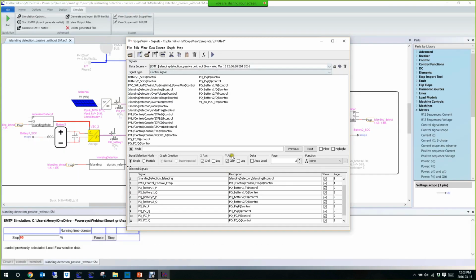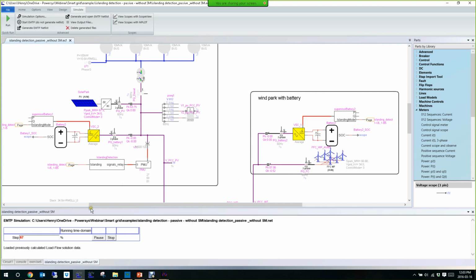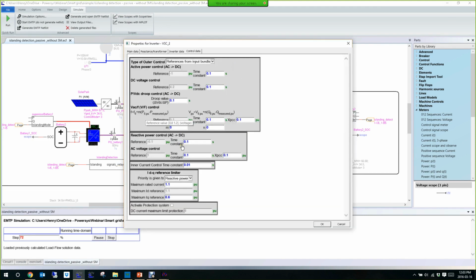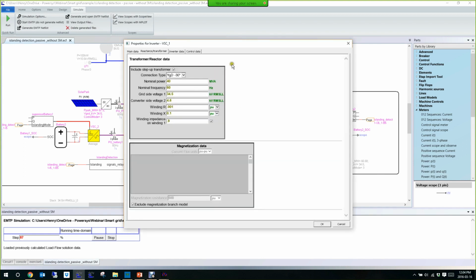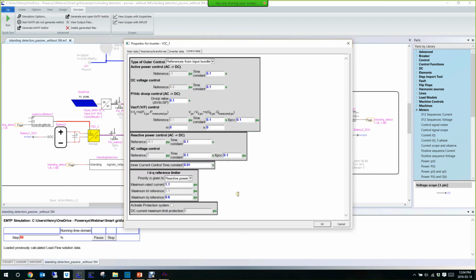Why is that? Well, because as soon as we islanded the network, we declared 2 slacks. So you have 2 slacks on your network, so it's over constrained, and you have some power rotating inside the network. And why do we have that? Well, remember I talked briefly about the VF control in islanding mode. In islanding mode, you have to do what is called a droop control. And in that case, the real frequency also depends on the power you want to generate. So here we have to set M and N to some value. Look, I will put some typical values, so that all the DGs of the grid will produce almost the same power and reactive power. It's not true for everything, but at least they will tend to produce the same.